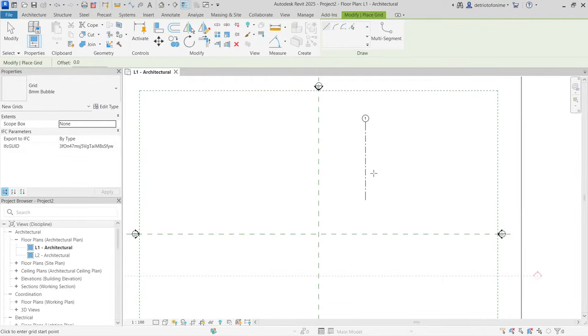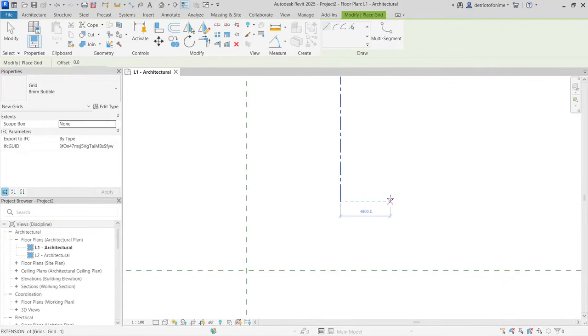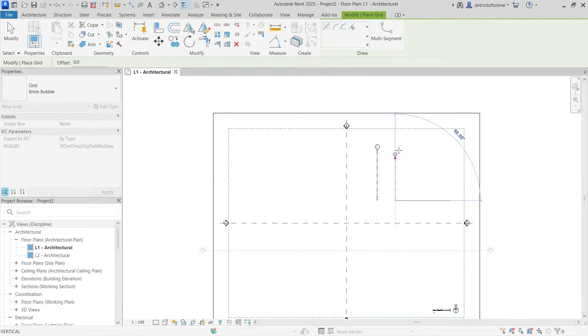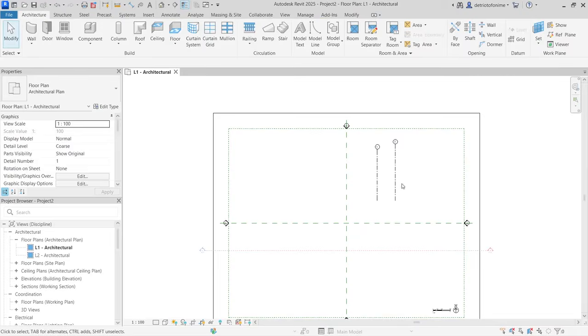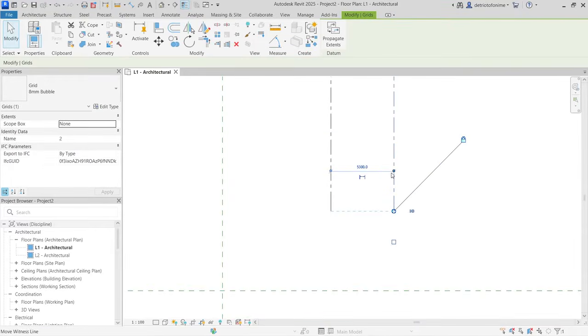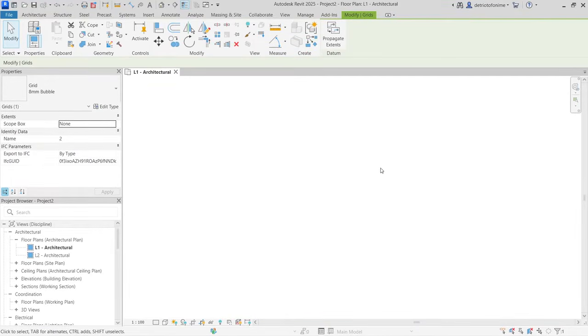Now the space between the very first grid and the next one is 3.725. Let's say it doesn't matter now, just click another space, and once you start clicking, Revit is going to give you a marker like this. Click once, draw the second line up, and once you're done, select the second one and then change the dimensions.